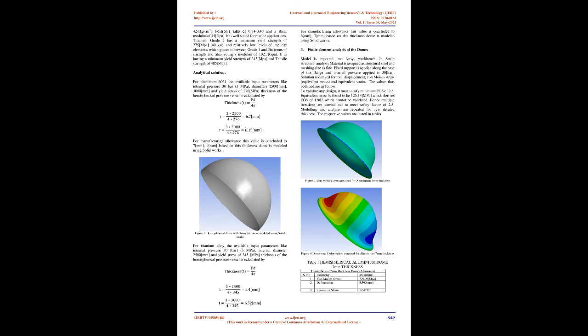There is a 1 bar increase in pressure for every 10 m of depth. At one point during its operation, the dome of an underwater vehicle is subjected to a pressure of 25-40 bar. As a result, qualification of this dome for the pressure is required. Hence the dome is designed to take up a pressure of 30 bar.